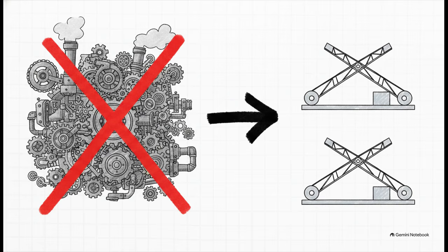Multiplying a weight by 1 just gives you the weight, and multiplying by 0 gives you 0. So they completely replace heavy multiplier circuits with simple, highly efficient multiplexers. A multiplexer is basically just a switch that either lets the weight pass through or blocks it based on the input. It is a massive shortcut for hardware efficiency.